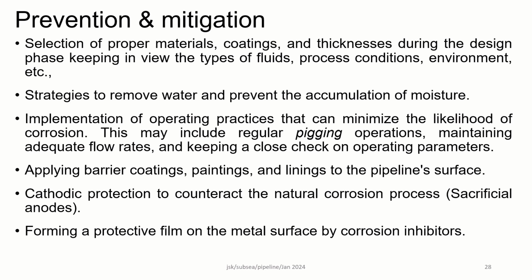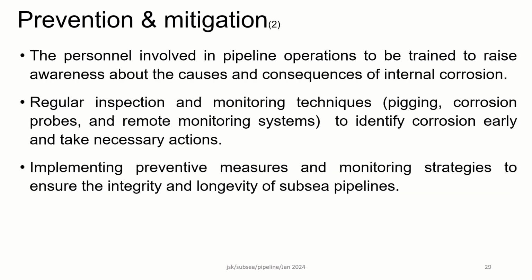So it goes with proper material selection, strategies to remove water stagnations, improving operating practices, that is by pigging and other things, applying barrier coatings, paintings, cathodic protection, forming of protective films with the help of corrosion inhibitors. The personnel involved are also to be trained to take care of the consequential internal corrosions, regular inspection and monitoring techniques such as pigging, probes and remote monitoring, implementing preventive measures and monitoring strategies to ensure the integrity and longevity of the subsea pipelines.